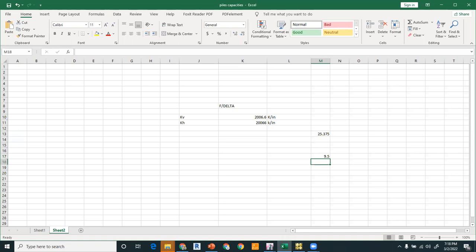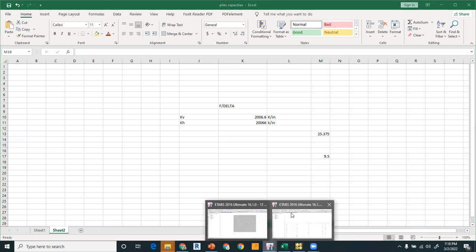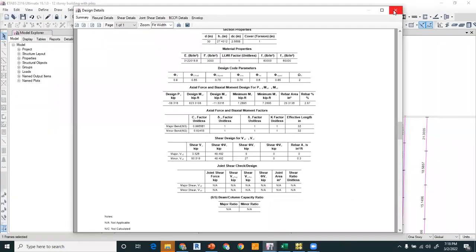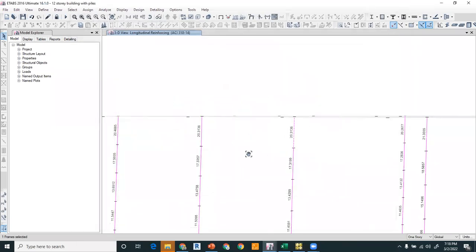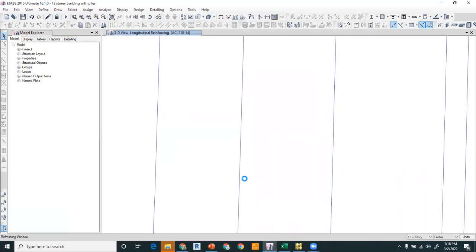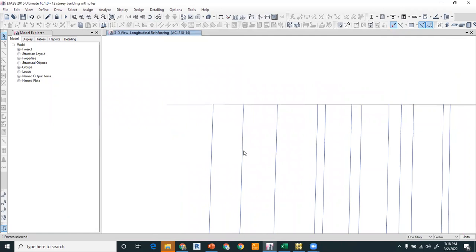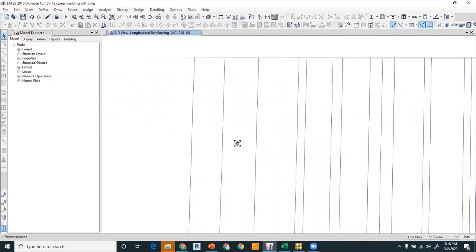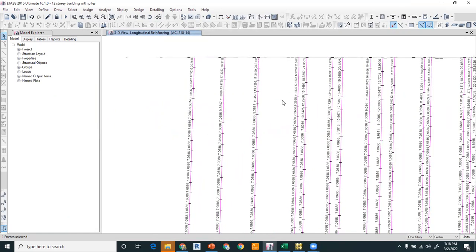So it depends upon the designer, because you can see that there is not much variation in the reinforcement after the 1/3, because you can see it is decreasing, and it is almost 1%. It is not the same for the piles, just like in the columns. This is greater, this is 20, this is 17, 13, and now you can see this is constant 1%, right?